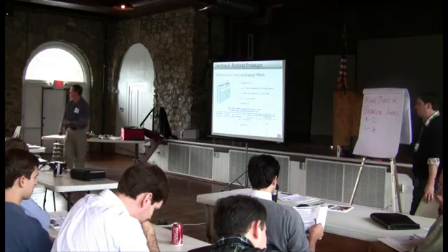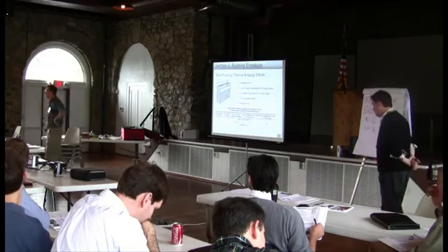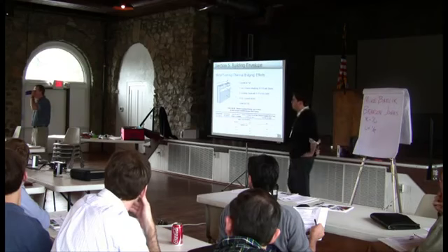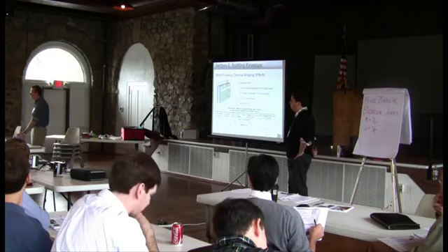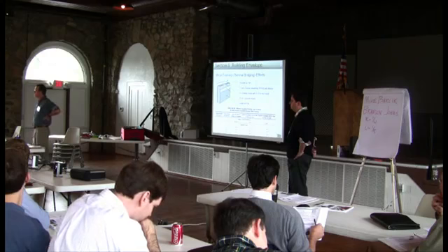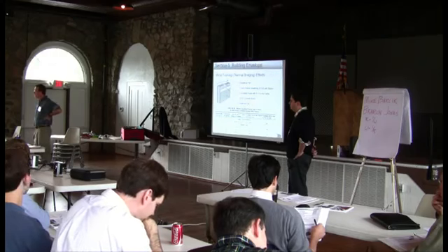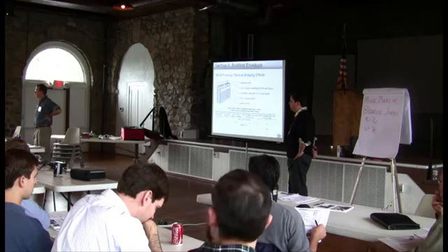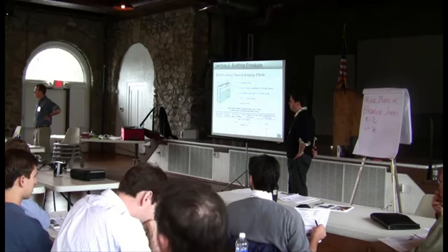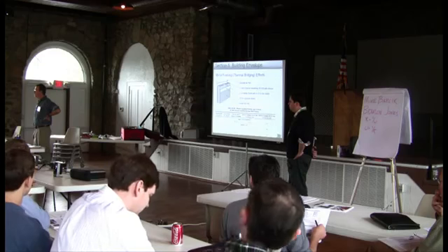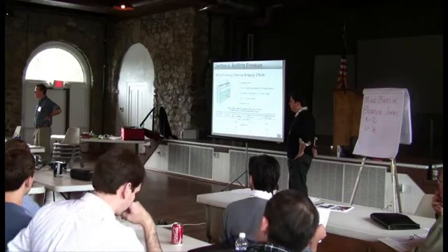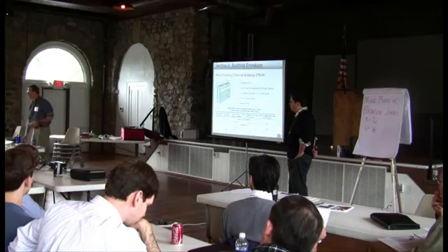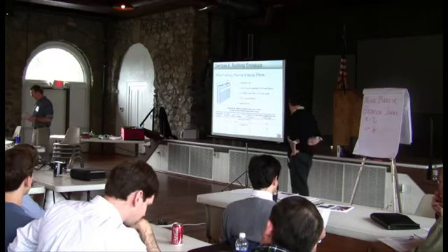Let me ask you a question. Please. George and I do a lot of metal buildings that aren't really just metal buildings. I mean, they're commercial buildings, finished on the inside with just boards and all that sort of thing. I've got a system that I've been using that I think takes care of that effect. But I am insulating the cavity instead of the outside. But I'm putting exterior gyp board on the outside of the metal studs, then interior gyp board on the inside. Because you need to seal the cavity. Right. Well, I like that part. Isn't that similar to what you're doing there?